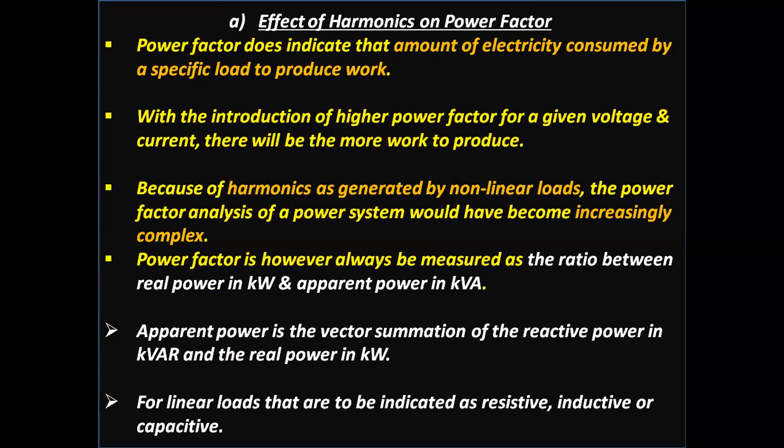Because of harmonics generated by nonlinear loads, the power factor analysis of a power system becomes increasingly complex. Power factor is, however, always measured by the ratio between the real power in kilowatt and apparent power in kVA. Apparent power is the vector summation of the reactive power in kVAR and the real power in kilowatt.